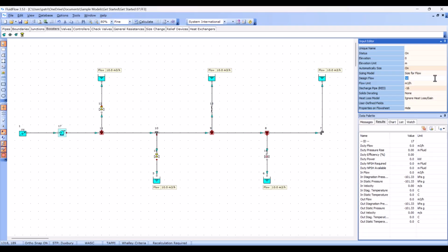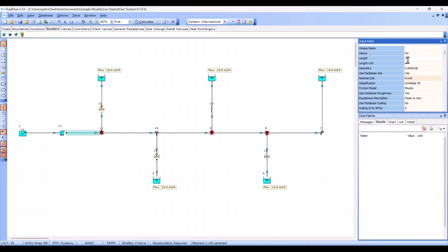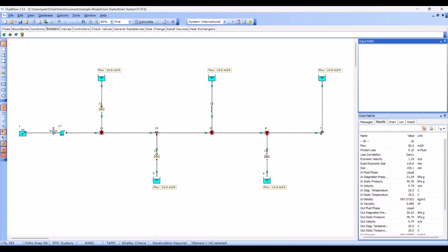After placing the pump, you will notice that the model now includes a suction side and a discharge side. We need to be careful here, though, as the discharge side was previously modeled as a single pipe. By adding the pump, the software automatically splits the existing pipe length into two. To rectify this, let's adjust the discharge pipe back to 30 meters. For the suction side, set the pipe length to 3 meters, assuming the pump station is located adjacent to the suction vessel or the tank.